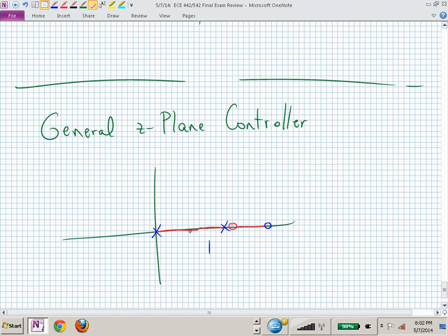Now I don't know what I'm going to erase. I knew it. So we need to add another pole, don't we? That zero is not in a bad spot. But we also need to probably put in, we do need to add another pole so that we have a causal controller. Now we may have to just kind of hope for the best, because eventually, we'll get there, won't we, between those zeros. These two are going to meet. This one's going to go off there, and these two are going to go here.